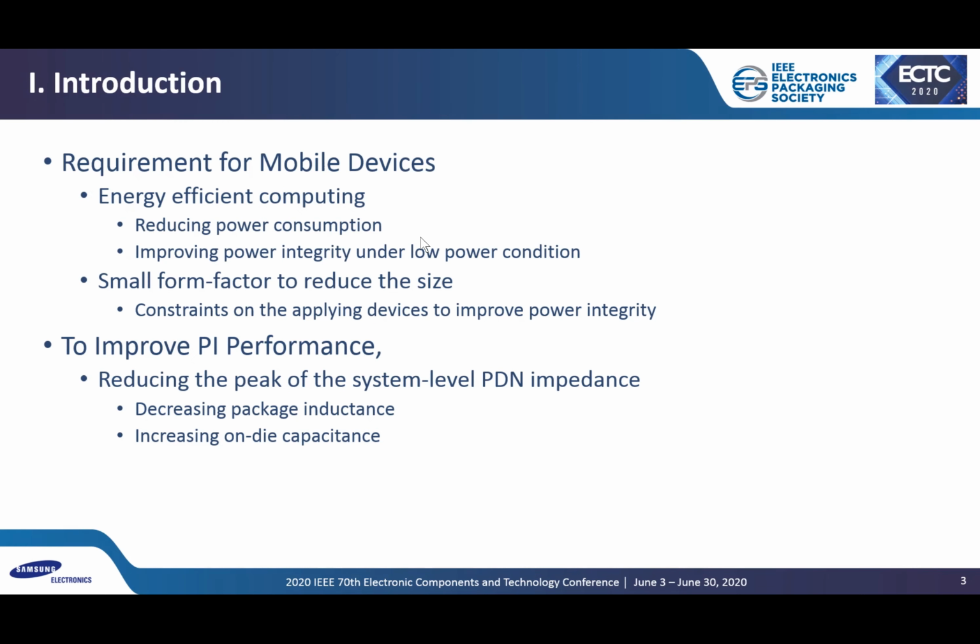Since neuromorphic computing cores like NPU in mobile phones require energy-efficient computing, the importance of reducing power consumption and improving PI under low power condition is increasing day by day. However, it is very important to have a small size for mobile devices. Naturally, this leads to constraints on the use of the devices to improve power integrity.